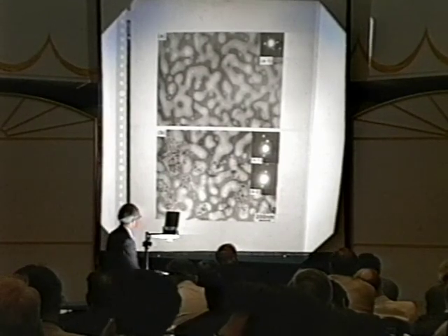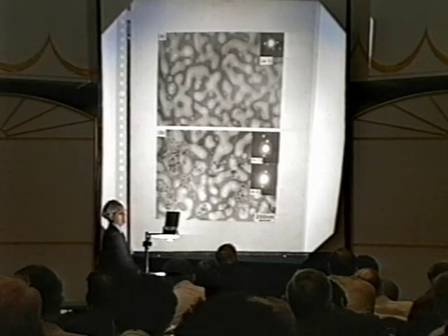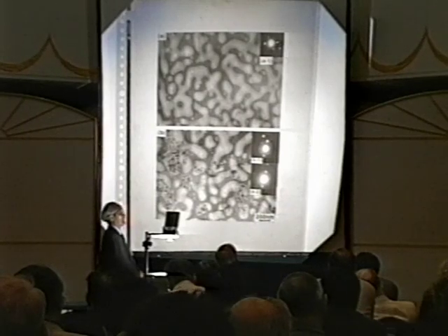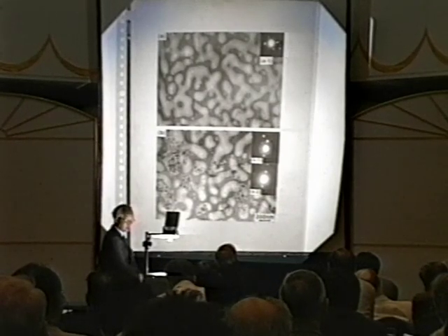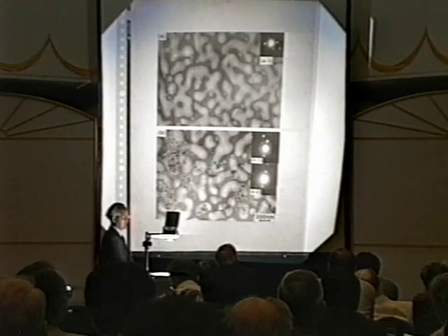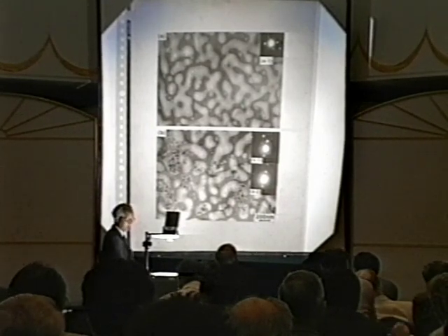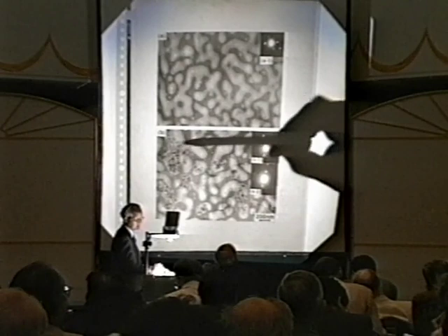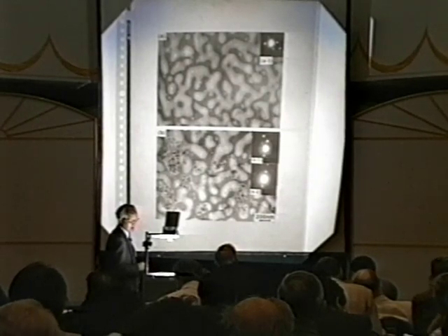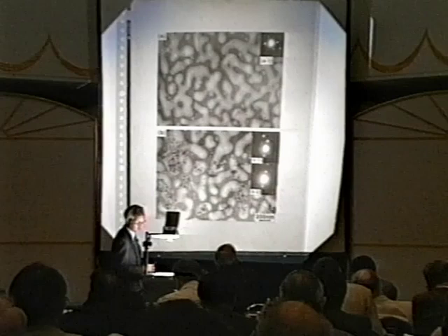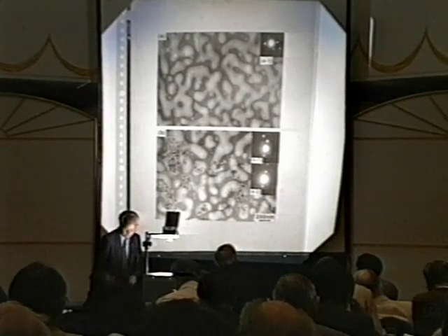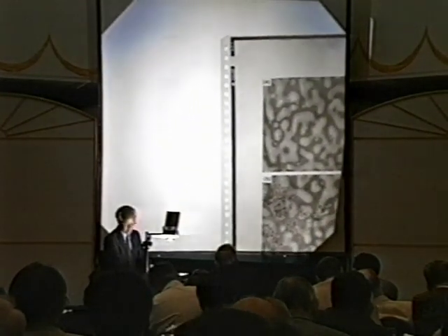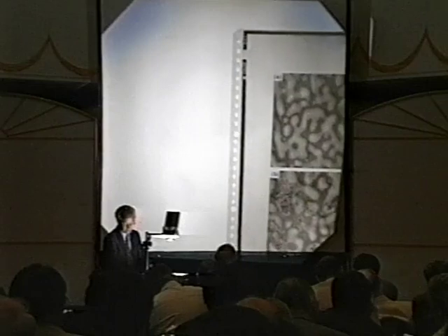And as far as I know, the transformation from single crystal to polycrystal in very pure aluminum cannot be observed without melting. So I conclude that these speckled regions appeared because of the melting of the aluminum, which is never observed in the hydrogen implanted case.